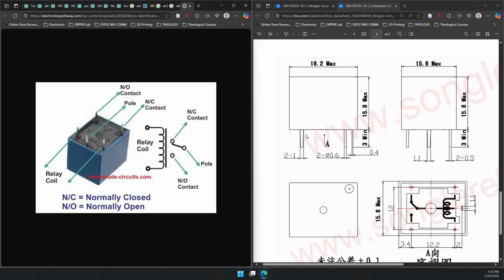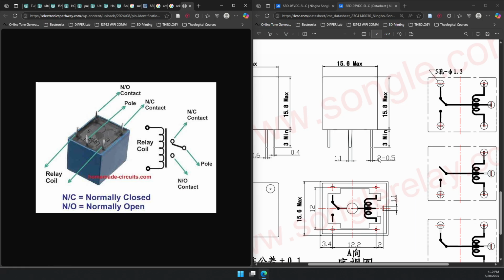And if I come here, I'm told that these 2 pins at the back, 2-1, means that 2 pins are 1 mm. Over here, I knew it's 1.1 because here is just 1.1. Their control pins, right? They're really coil pins. And because those ones aren't carrying much current, they've made them smaller. And then the ones carrying current, sorry, let me pause and take this call.